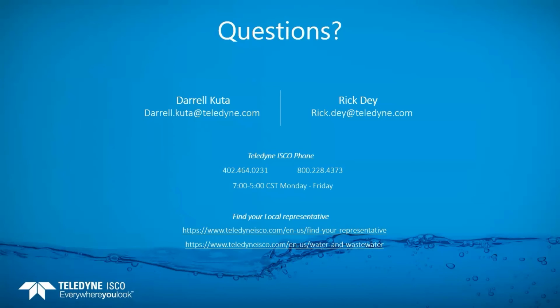Go ahead, Daryl. Yeah, Rick, I want to add something on that. When you send the text to wake up the modem or the Bluetooth, it will send you a text back letting you know that it's available for you to connect, and then it'll keep that window open for 20 minutes. So you just wait for that text, you get the response back, then you'll be able to call it up or use the Bluetooth. And if you are on site, if you cycle power, it automatically wakes up the window to allow you to call the site that way as well.